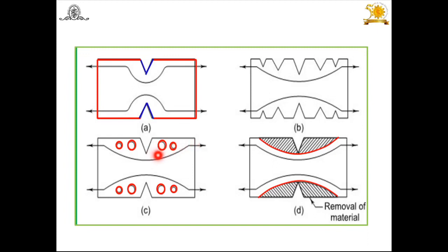That means stress concentration gets reduced. And third one, by removing this material, directly from the head section, this removed material again reduces it. That means there are three options: multiple notches, drilling a hole, and removing the material.